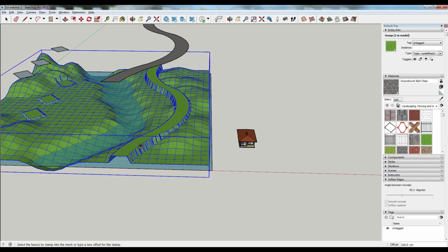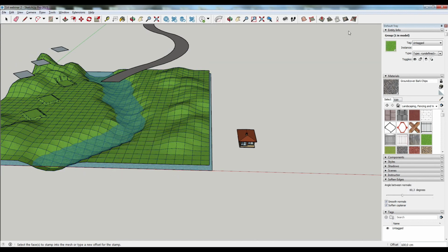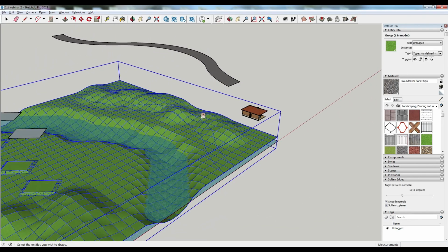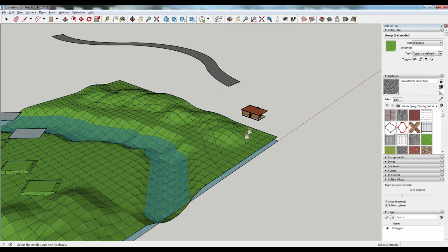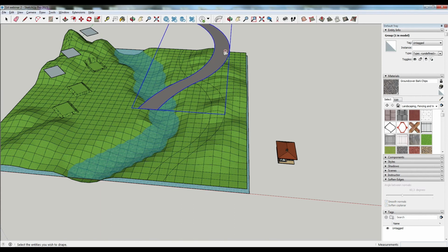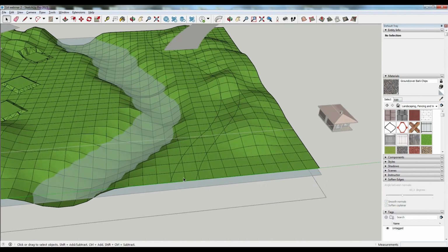The other way is to use Drape tool, which would be more convenient. I will show the surface and then the terrain, and now I have an exact copy of the geometry placed on the terrain depending on each and every height of every point of it.